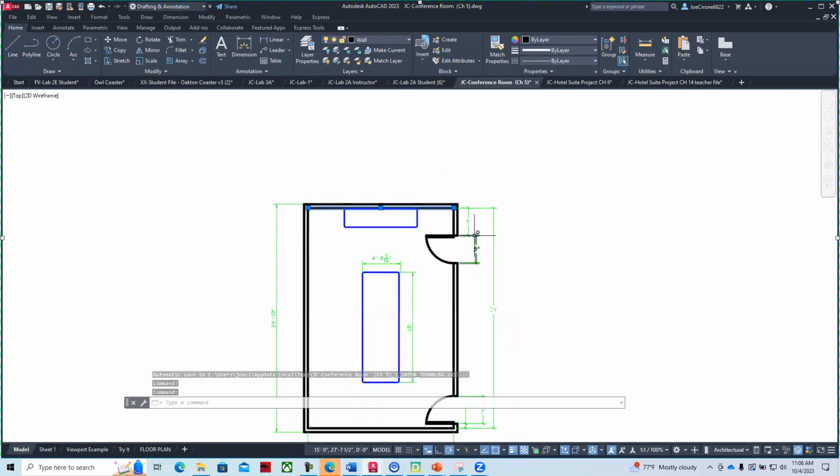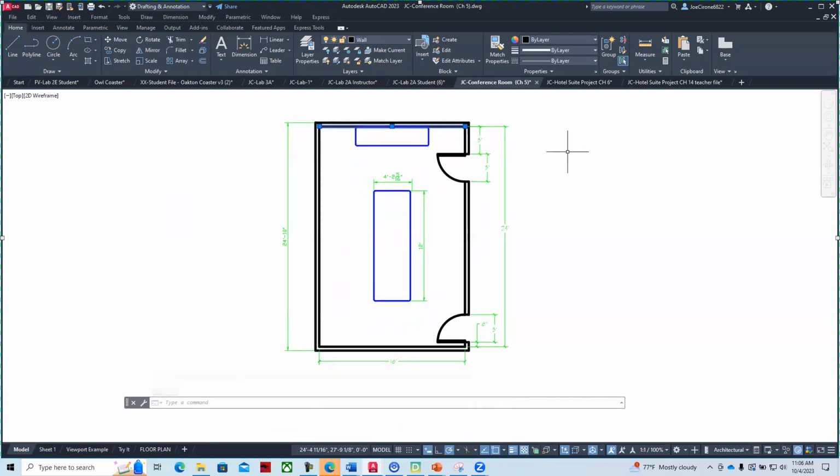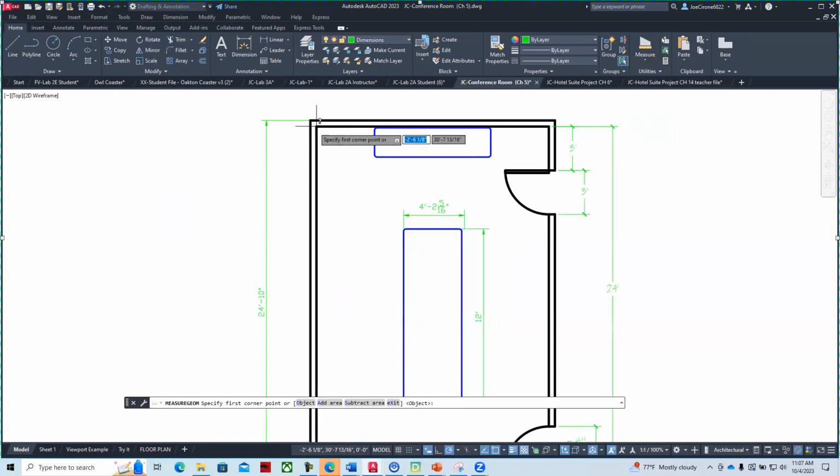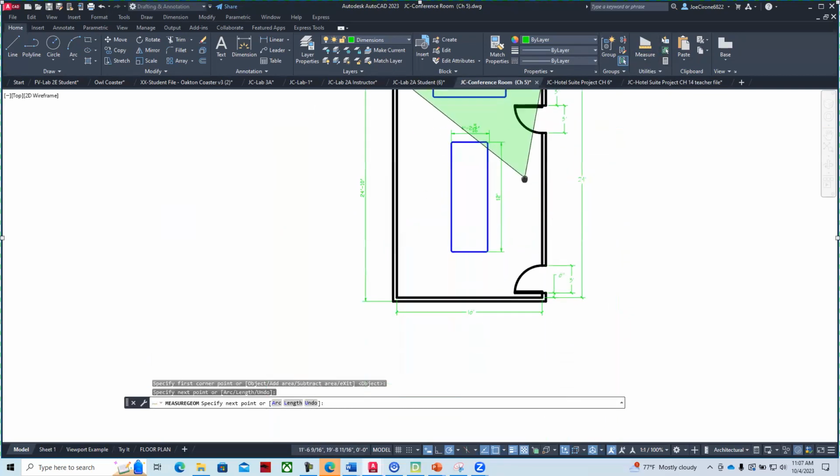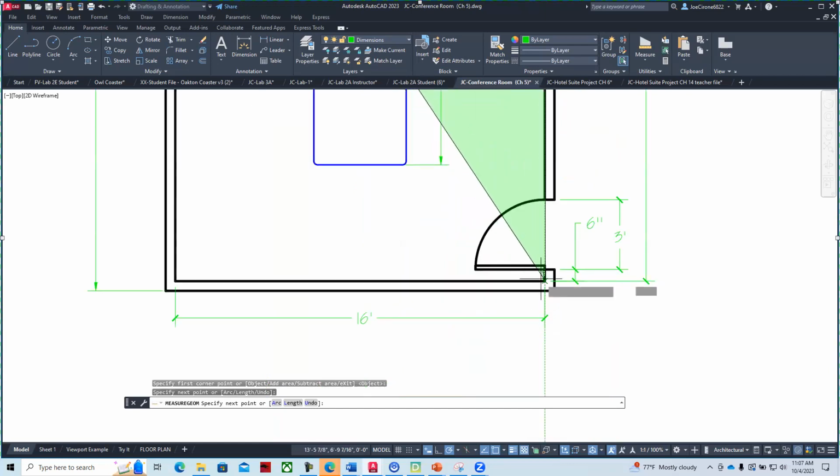And then we can also calculate out room sizes. We can go to our utilities, and let's say we wanted to put hardwood floors in. We could go and measure the area. There it is. Again, you want to use O-snaps, but what's nice about using CAD is that it will figure things out even if the room isn't square.